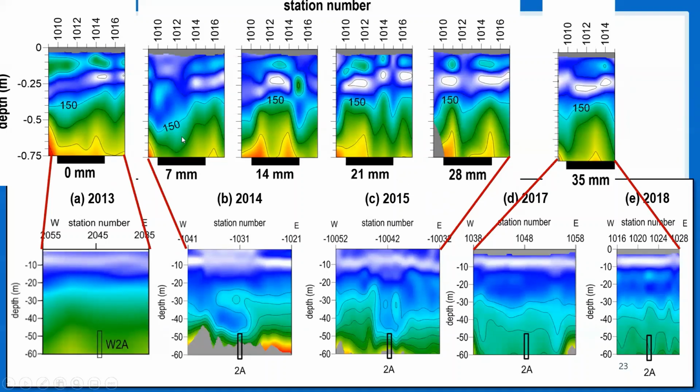So in the 7 millimeters, we saw a decrease on the left side versus a normal state of velocity, if you will, on the right side, then increases, then another change where one corner saw a decrease versus the other corner, and then we saw slight increases on both corners. This seems consistent with some of the changes we saw in 14 and 15, where the distribution of load on the void was all changing over time.